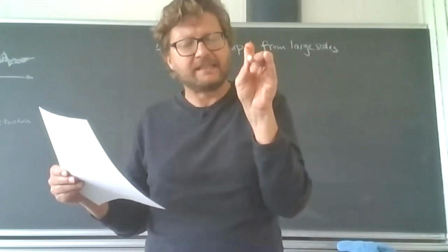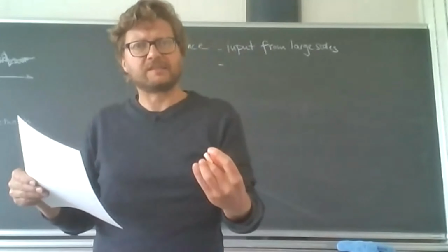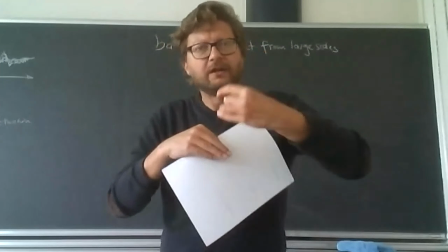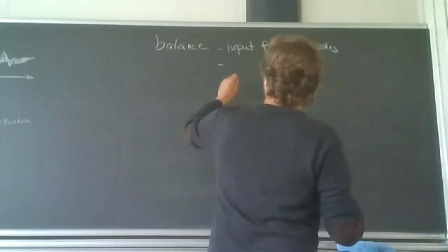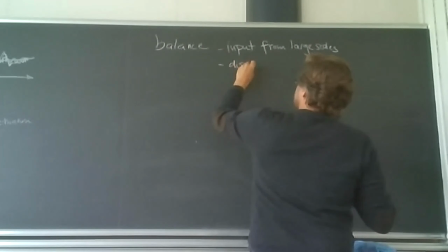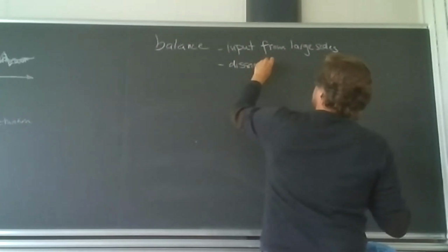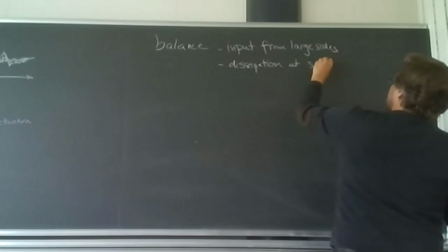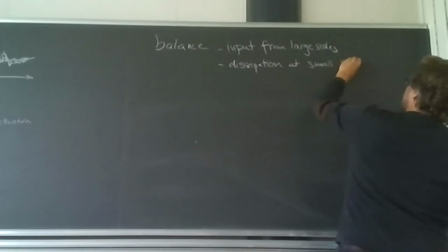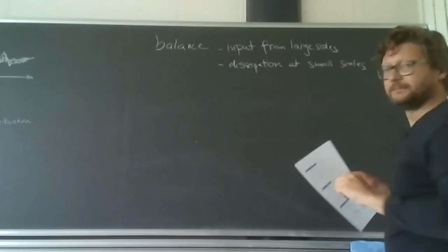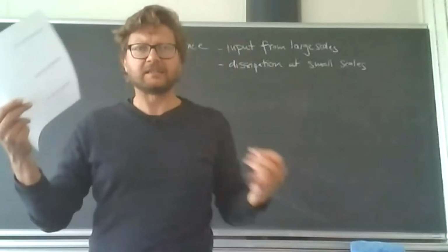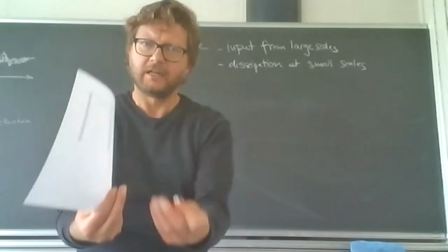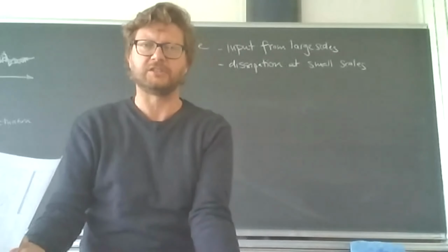The smaller an eddy is, the more viscous losses you have. The smaller an eddy is, the higher the shear rates, the more the viscous shear stresses. So dissipation at small scales. He had a process he didn't understand in detail, but he knew there's large energy coming in, and there's something very small which drains this energy.